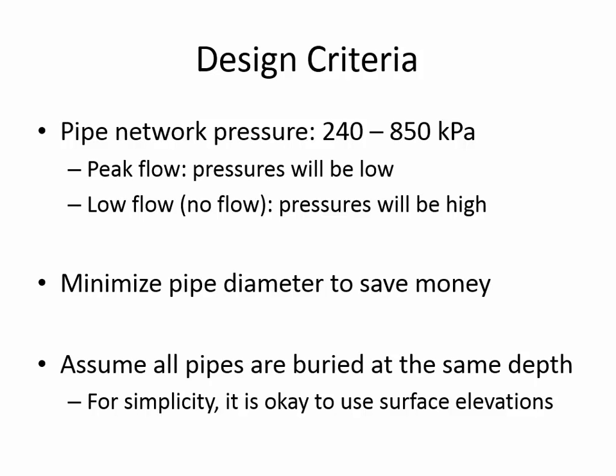And I'm going to be looking for evidence of optimization. I've graded this project enough times that I can look at a network and see if you've gone through the process of making this pipe bigger, making that one smaller. And there's an automated tool within WaterGEMS where you can tell it how much each pipe size costs, and it'll go through and automatically try to minimize the cost. If you want to figure out that function, you're welcome to use it, but I'm not going to be teaching it to you as a standard course of the project. It's kind of like an advanced tool, although there have been a handful of students through the years who have used that tool.